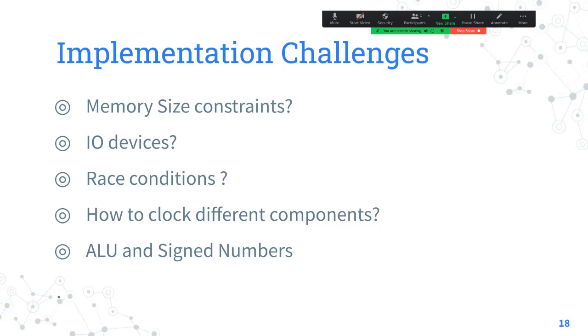Till midterm, before we included the keyboard code, we had enough LUTs because we were using LUT memory, continuous memory. The design was easy. When you use continuous memory, there was no complexity in designing the memory part when reading the instructions and writing to memory, both instruction memory and data memory. But once we included the keyboard, the number of LUTs exceeded what we can implement on the small board that you have.